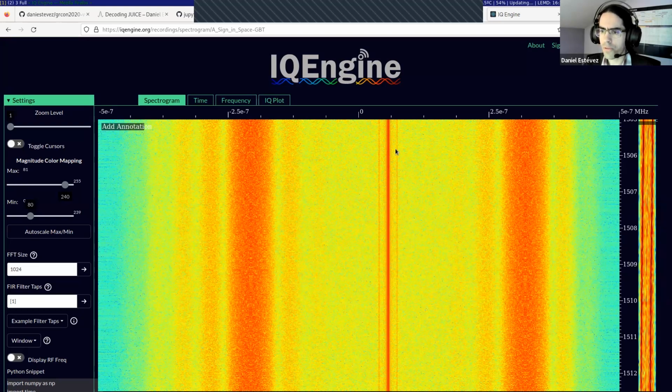And it's used for phase synchronization in the receiver, because in any kind of digital communications, the transmitter and receiver need to agree on basically some time intervals. So you can imagine that bits are essentially transmitted at regular timing, but the transmitter uses its own clock, and the clock is not embedded in the signal. So the receiver needs to monitor the signal in some way and to synchronize with the transmitter clock.